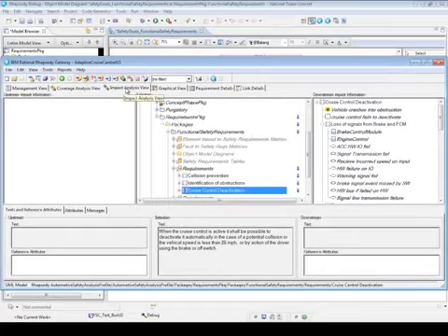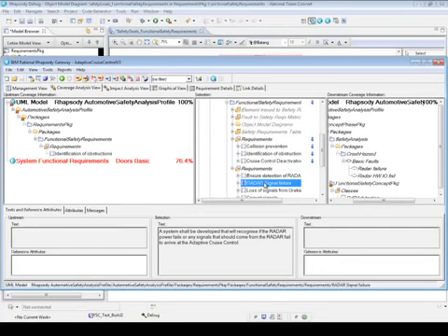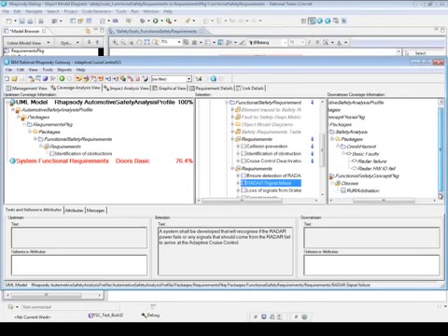If we take this lower down and maybe look at our radar signal failure, you can see that it links in with the safety goal to identify obstructions, covers the basic faults radar failure and radar hardware I/O failure, and it's linked to the radar arbitration, which is the subsystem that can negate this fault. In this instance we've covered 100% of the safety requirements within this particular model. At the moment, of the system functional requirements, only 76% are covered.